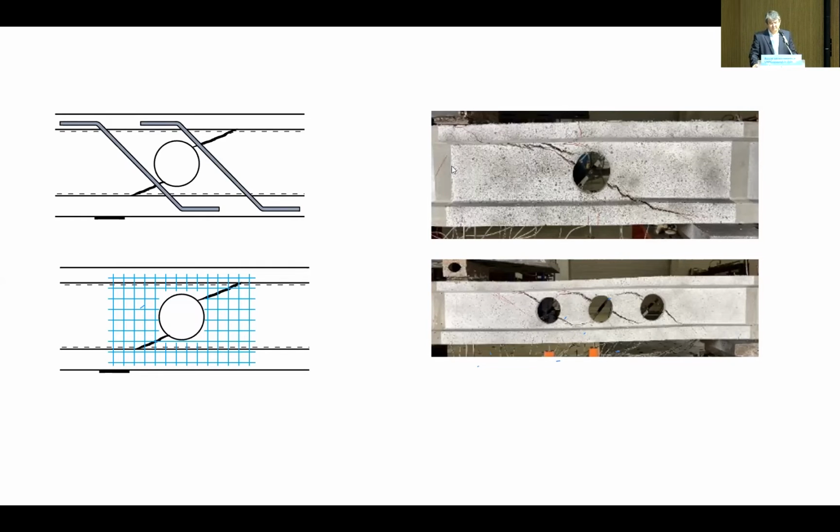I have a question. Usually when we go with 3D printing with the UHPC, steel fibers are kind of a hurdle in the injecting equipment. How can we solve that problem? Addition of the fiber to the UHPC causes more friction between the pipe surface and the material itself. So it's not easy, but we can solve the problem. With more flow, it is possible to use the material for 3D printing. So I think it's some research on how much the viscosity of the material is.